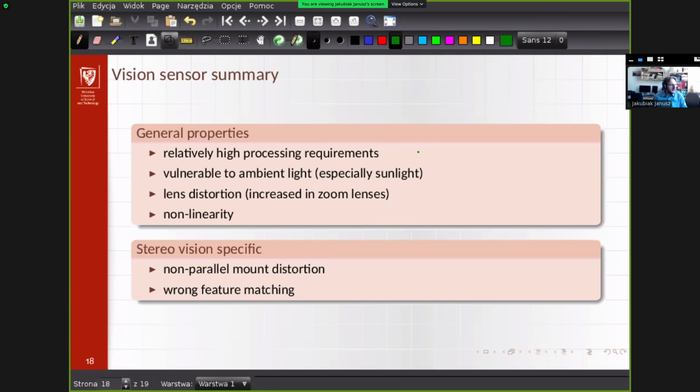As you already said before, for example, from sonar, you can get like a few measurements per second, maybe 10, maybe 20. With laser scanner, you get, let's say, about a few thousand single distance measurements per second, while in camera you get millions of points, and of course processing that requires much higher processing power, much better microprocessor than the other sensors.